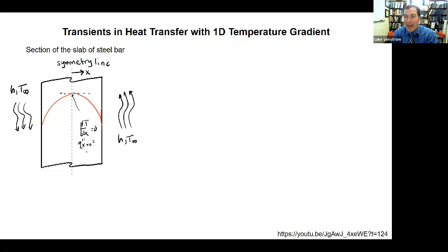So this is going to be a really handy boundary condition for us when we go to solve this problem. We can use that to our advantage. So even though there is heat transfer in the bar, it's got to be emanating from the center and moving towards the surfaces symmetrically on both sides, so that there is no actual transfer of energy across the symmetry line. No net transfer of energy. Does that make sense, what I just said? It's kind of important that you're able to see that. Okay, so lines of symmetry are our best friend in heat transfer because they simplify problems down.